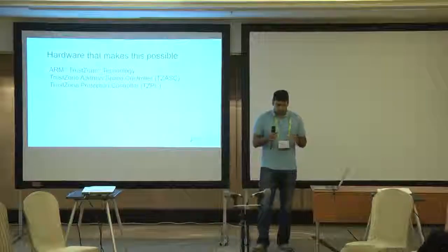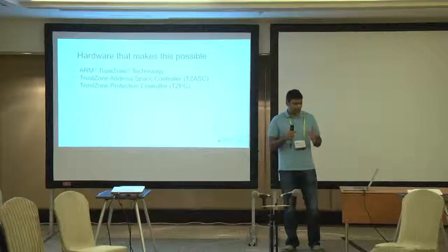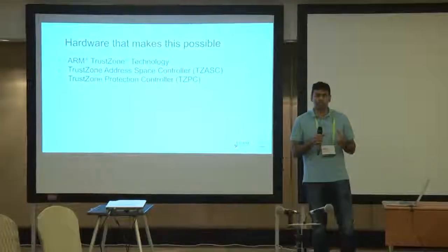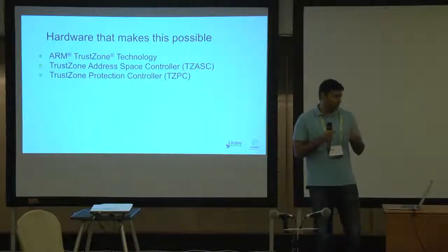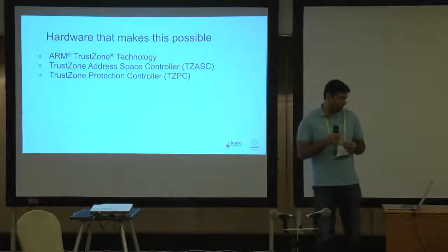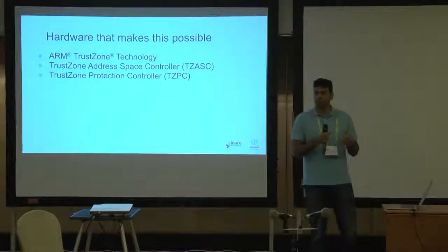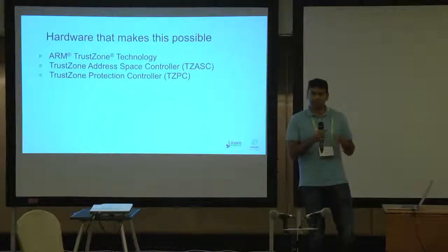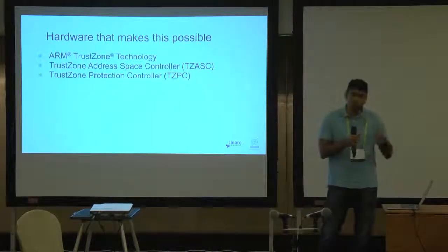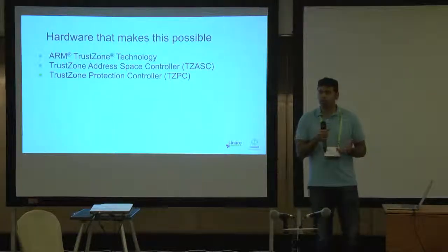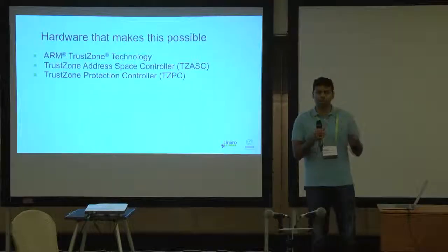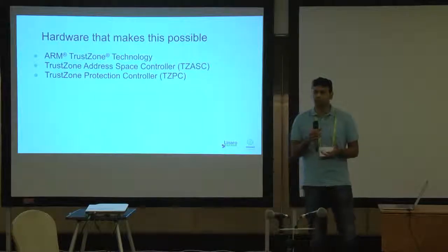Before going to the secure playback, I want to understand the technology that makes this possible at a hardware level. So you have the ARM TrustZone technology, and you have the TrustZone Address Space Controller, an IP that can protect blocks of memory in the DDR. And you have a TrustZone Protection Controller, another IP that can protect certain secure peripherals on the SoC.